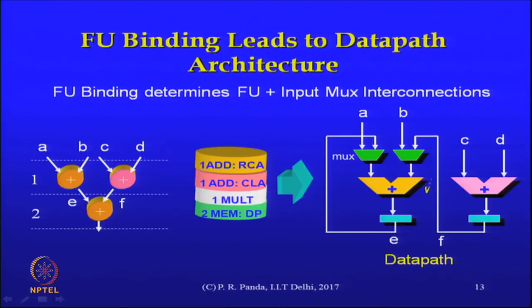First of all, these two resources are used, right? These two adders are used. Then remember, there is a reuse of that adder being implied by that sharing of that adder across time, and therefore, that may lead to a mux that is inferred at the inputs of that adder. The second adder does not need a mux because there is only one addition being mapped to it anyway. Now, I have the adders, I have these muxes, again they are possible muxes. What else is there? What kind of multiplexing do I need to do?